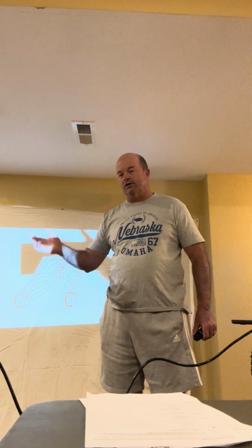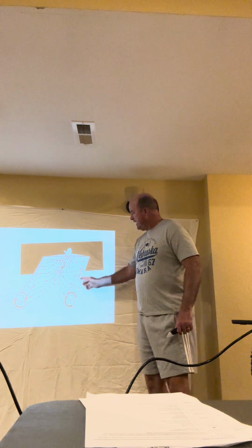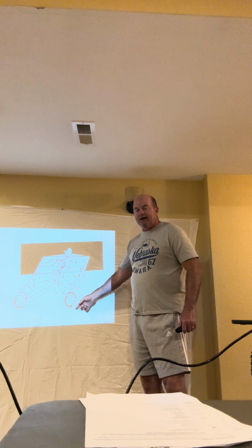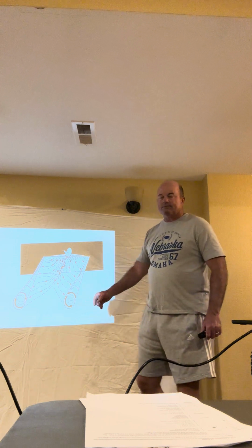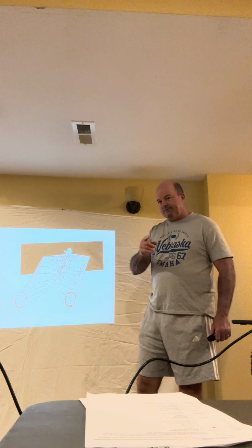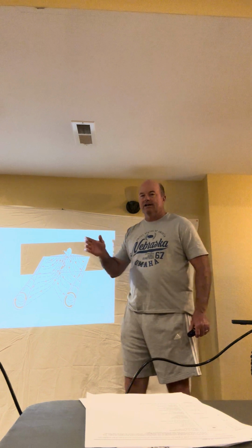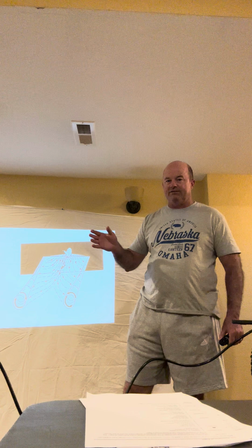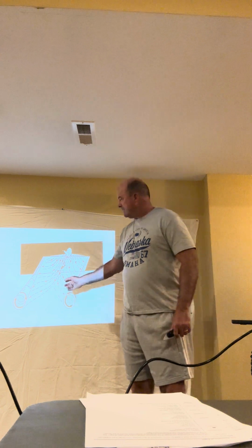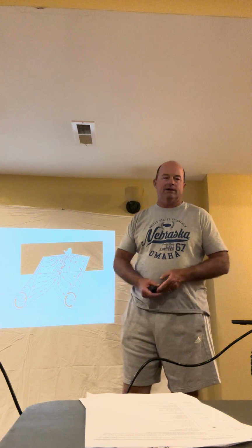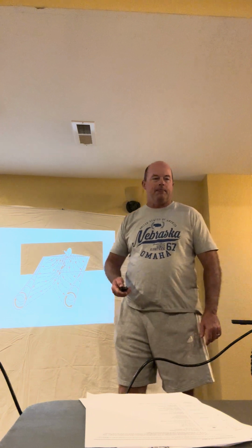Because it's kind of circling around, as you see right here, and it's hitting the top, so it's pushing it down. And that's why you have winglets, right? Winglets come straight off the edge of the wing, and that apparently increases the efficiency of the airplane by about 15% because it eliminates or reduces wingtip vortices. So anyway, pretty cool stuff.